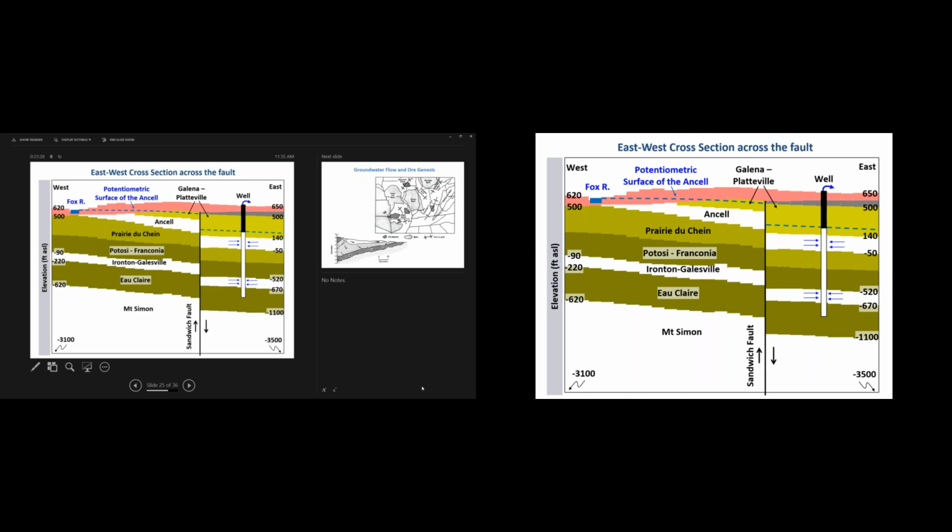Unstructured grid does have an option that lets you toggle on something that accounts for geometry of layers, and that's all I can tell you. I don't know what kind of voodoo it does and if it would try to restrict flow here or not. I would be very concerned with trying that, but that may be something to look into. I've never tried toggling that one on. Yeah. So with the finite difference model, we have our layers doing all these sorts of different things based on the geology.